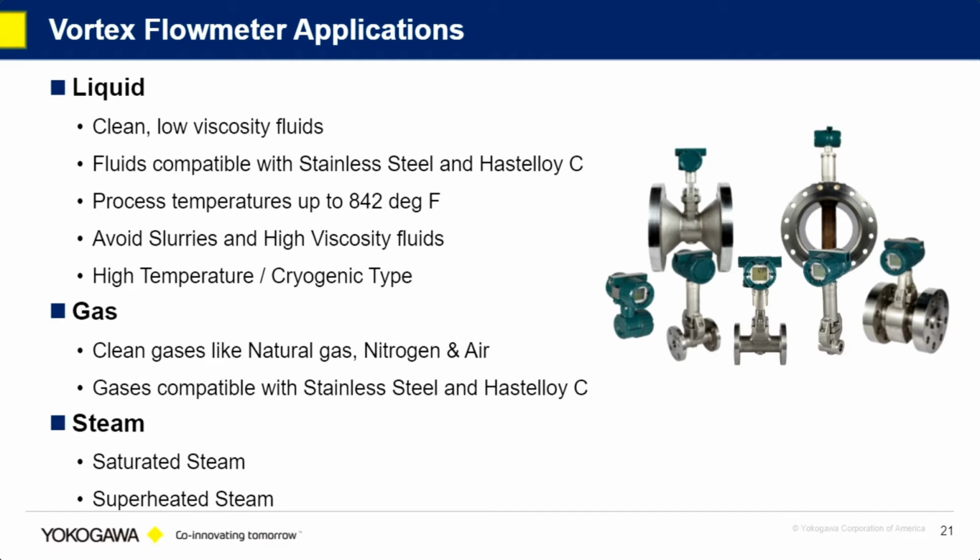So vortex meters are great for liquid, gas, and steam applications. In liquids, we like a clean process. Low viscosities are ideal, but we can do a high viscosity application as well. We have our sizing programs, and with a high viscosity application, it limits the vortex formation. So if our velocity is high enough to overcome the higher viscosity, we may be able to measure it. We don't want to shy away from those applications with a vortex, but it's best to contact us and let us run our sizing program and see if it'll work